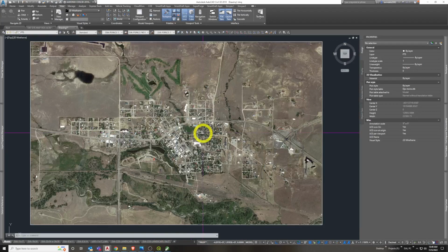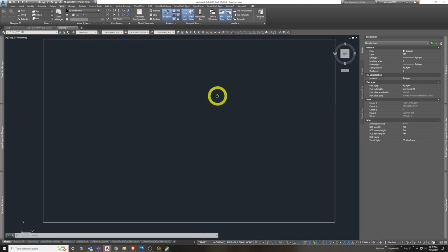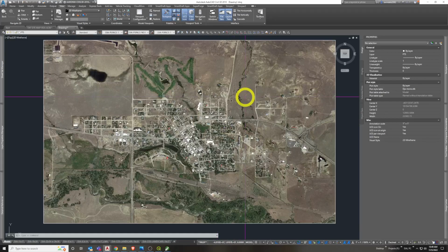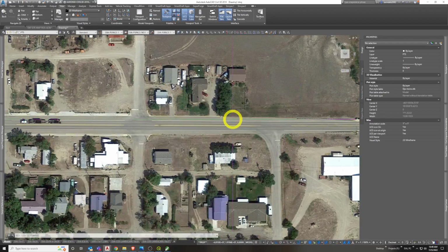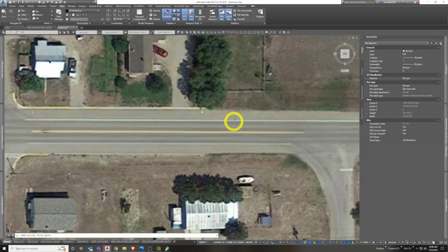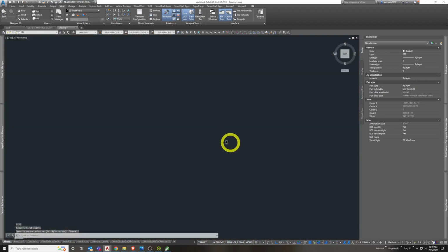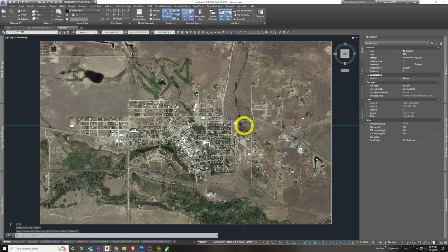You want to check it with whatever GPS data, any real survey data. You want to vet what you can to check and see if it's spatially correct. You might want to check one distance, maybe of a road, to see if it logically makes sense. It didn't scale it up. That looks about right, about a 32-foot road. It's not 5,000 feet. You didn't have that scaling issue. Check it with whatever you can.